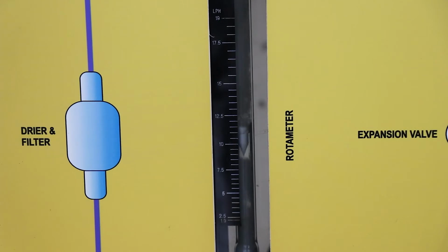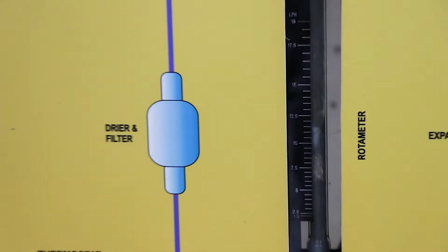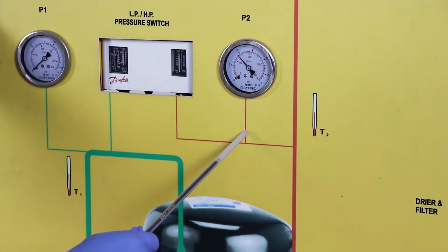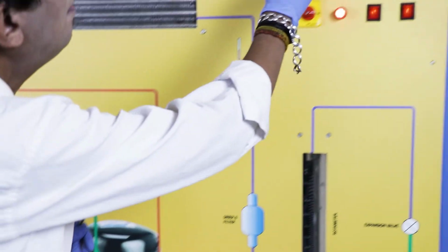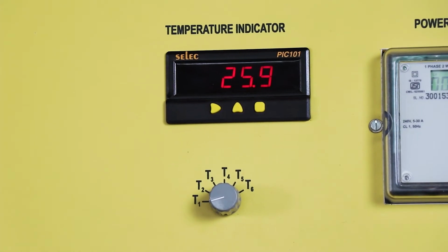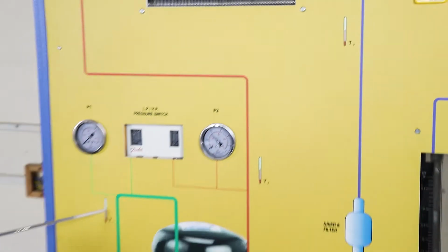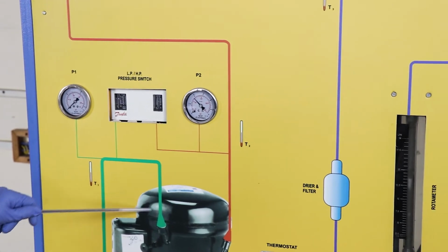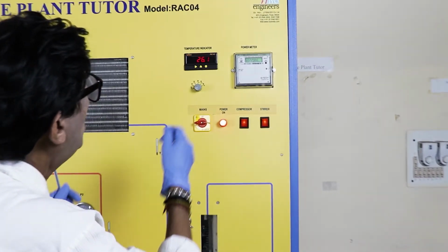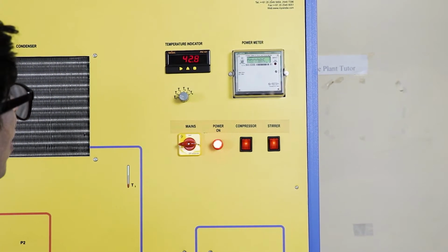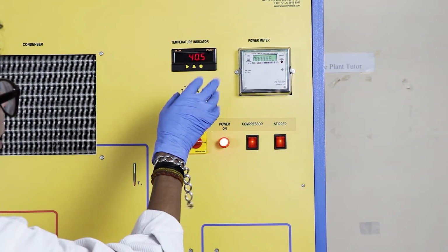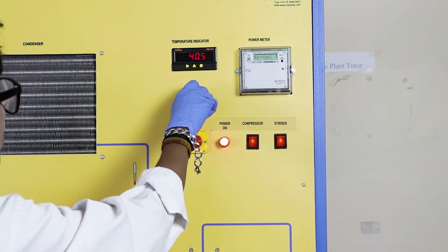This is giving the suction pressure over here, and this is the outlet pressure of the compressor, and so only two pressures, and the temperature readings here. This is the temperature T1 value, which is 25.9 degrees centigrade. This is T1, the temperature of the refrigerant which is entering the compressor, 25.26 now. So this is changing because the system is running. T2 is coming out to be something like 40.7, maybe 41, maybe like 40.5 at present. This is the present one.